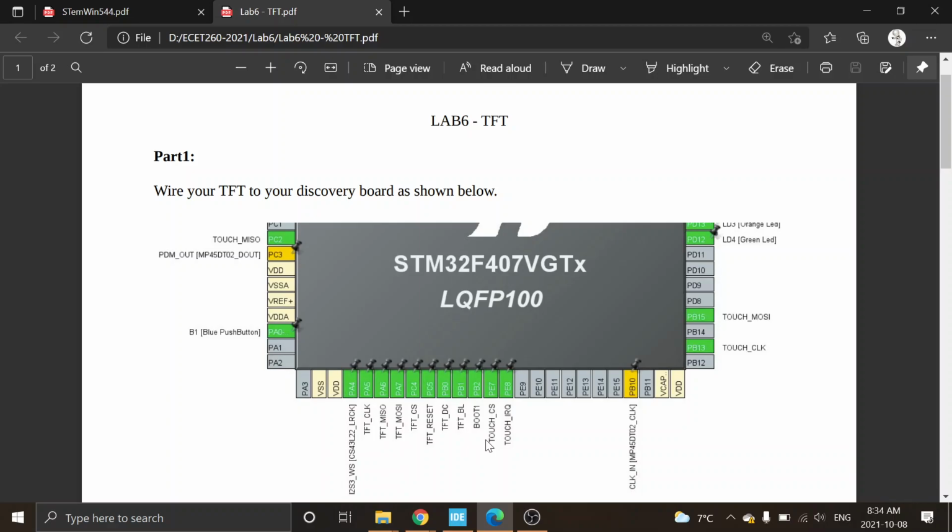So the display that we have here is a fairly inexpensive display. You're probably looking at under $10 out of China, and this one is based on a controller chip that's inside that's called an ILI9341. I think that's the one that Wayne has that you guys have been looking at. That's an ST7735, and I think as part of the labs you had to say, hey, it's an ST7735 in order to make it work, because the driver chip in behind it is an ST7735.